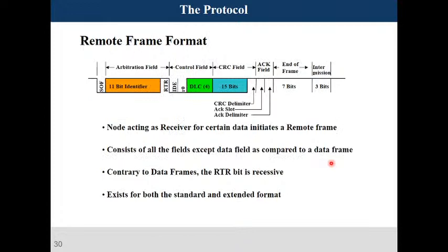Okay, then the remote frame format. Already I have mentioned that there is no data part over here. The DLC is always 0. It's mainly for getting data from the other node.